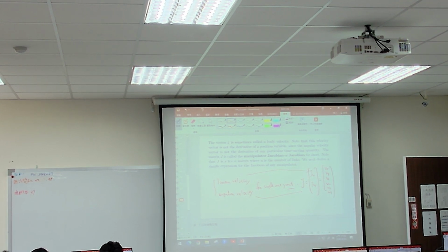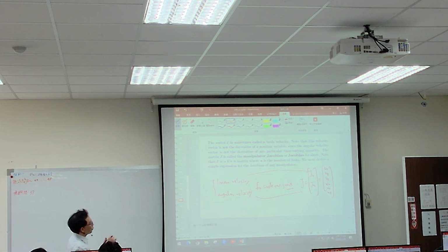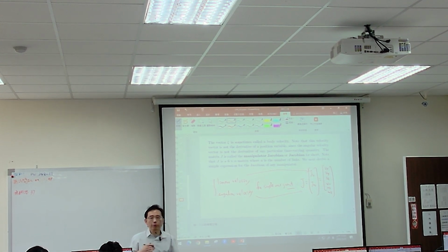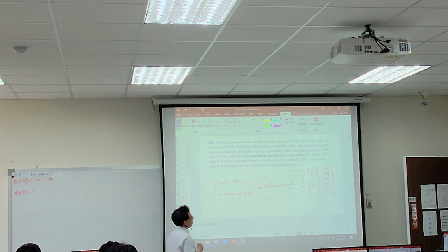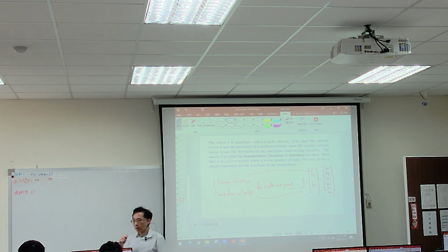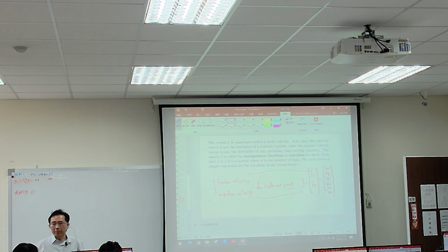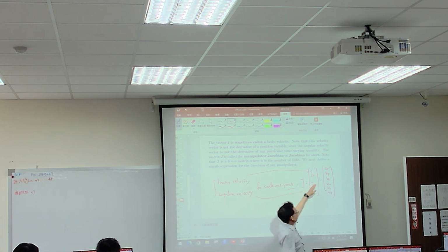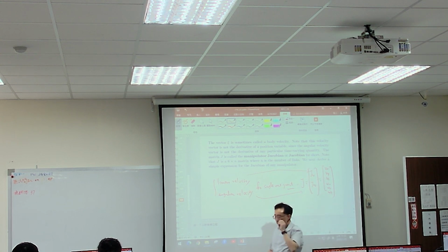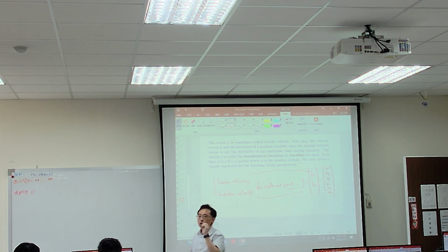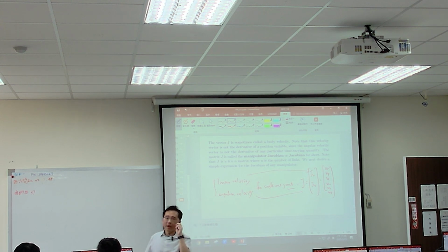It did not have this kind of representation, but I want to put it here to help you understand. Okay, so eventually the Jacobian is a 6 by n matrix, because for each joint, it will provide the elements to describe the joint linear velocity in xyz, and rotation or angular velocity in xyz.